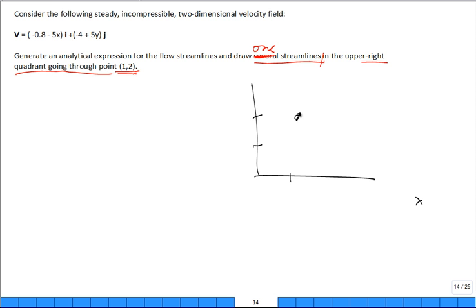And which direction did it want to head? In that direction. And so it may go like this. It may go in that direction and curve up. It may go that direction, curve down. I don't know what it does. But you could also, if we just chose that point to start and march time forward, true? You could mathematically choose that point, march time backwards to see where it was previously. And maybe it was over here previously. Or maybe it was down here previously. It's one of those, right? And so that's the streamline.